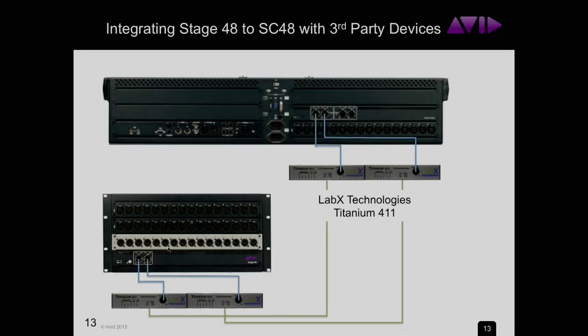This LabX device is an interesting device. I encourage you again to look it up on the internet, et cetera. It's one that's been really ruggedized, kind of with the rigors of touring in mind. It offers Ethercon connectors for the Cat5 connection and even Speakon style connection for the power, as opposed to a wall wart or anything like that. It's very robust. It's set up for truly professional, rugged applications. So have a look at it. And, like I said, this is just one example of third-party integration of AVB products and how they can help and complement each other.